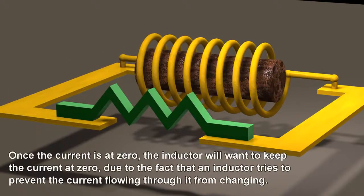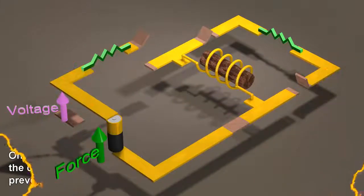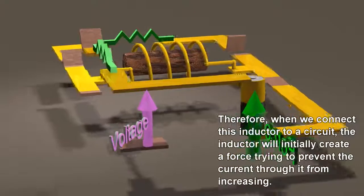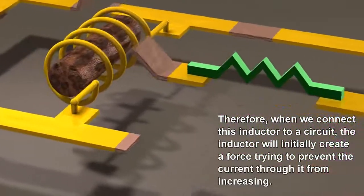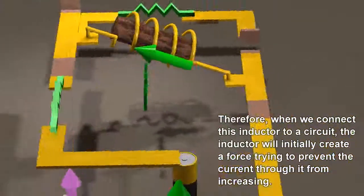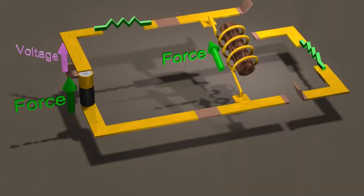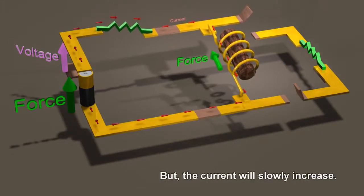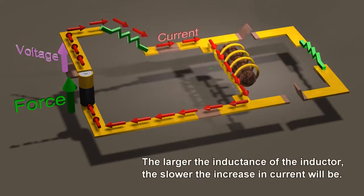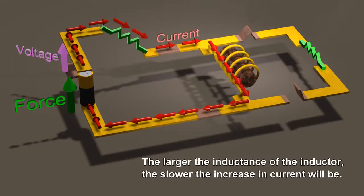Once the current is at zero, the inductor will want to keep the current at zero, due to the fact that an inductor tries to prevent the current flowing through it from changing. Therefore, when we connect this inductor to a circuit, the inductor will initially create a force trying to prevent the current through it from increasing. But the current will slowly increase. The larger the inductance of the inductor, the slower the increase in current will be.